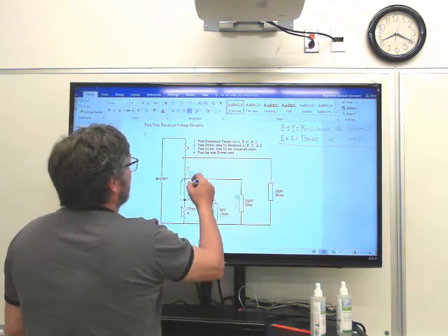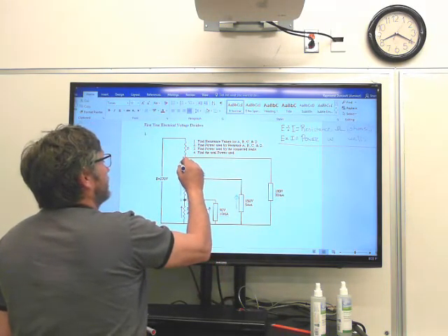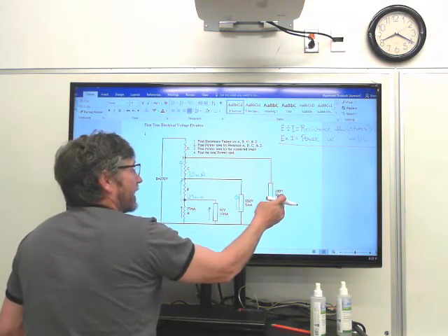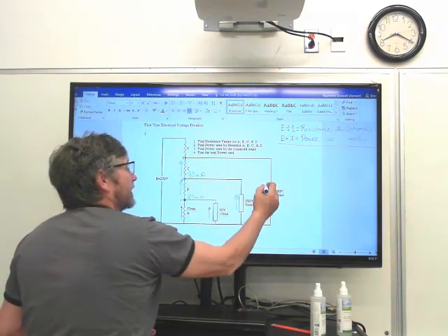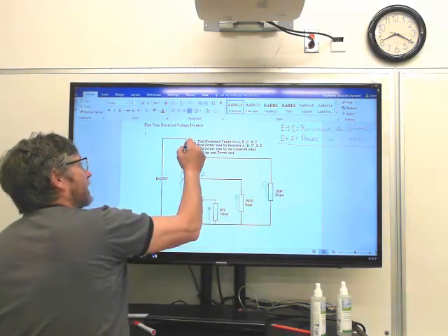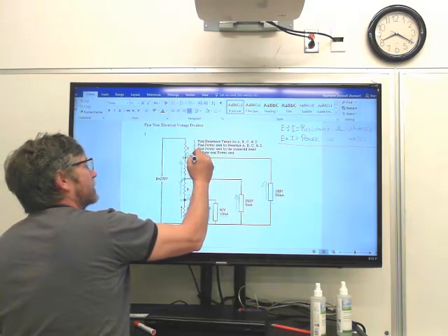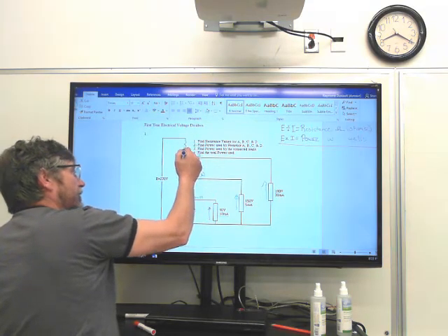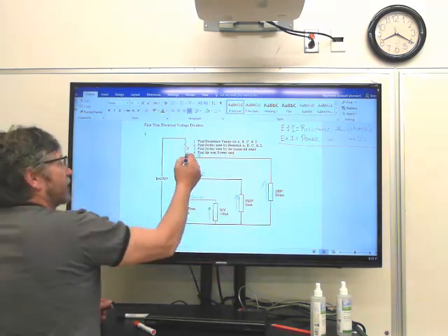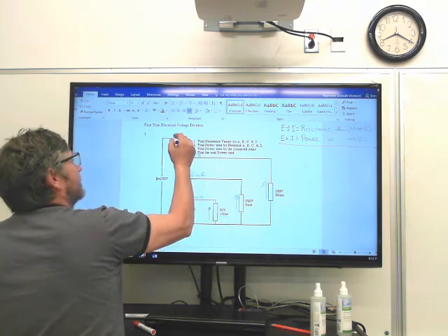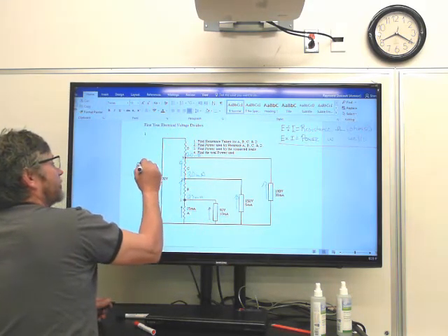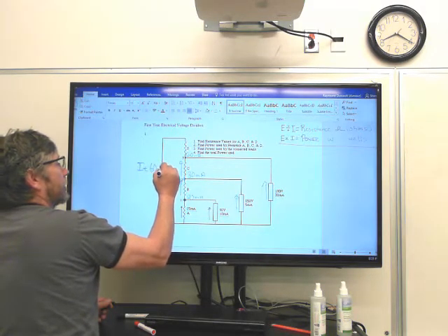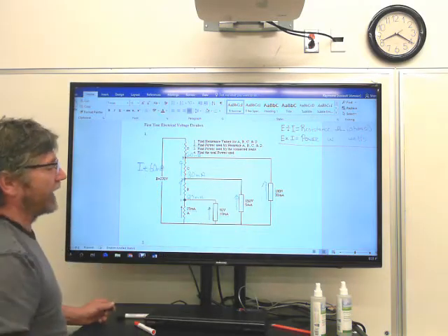And we go here again, 30 milliamps comes up through resistor C, comes into node 3, it gets joined with 30 milliamps out of this load resistor, comes in that way, up here into here, and makes 60 milliamps in resistor D. Resistor D is in series with this entire mess. Therefore, the current through resistor D is line current. So the I total for this circuit is 60 milliamps. Okay? So we've solved that beautifully.